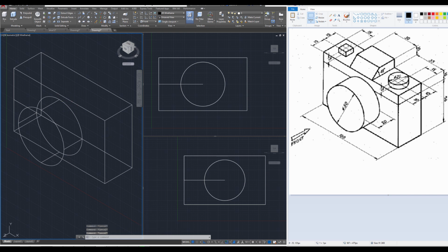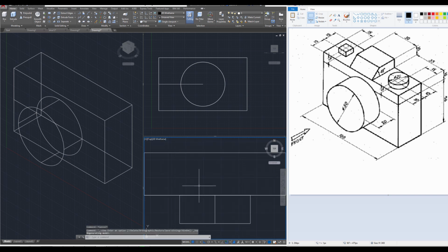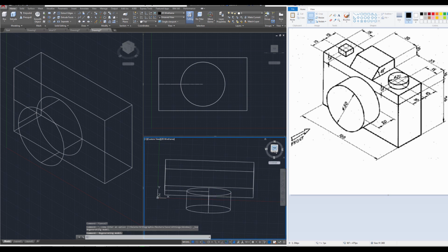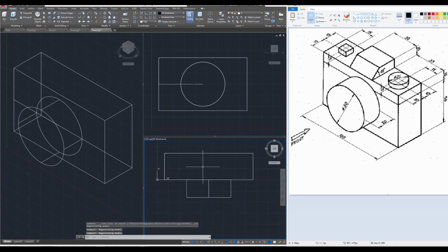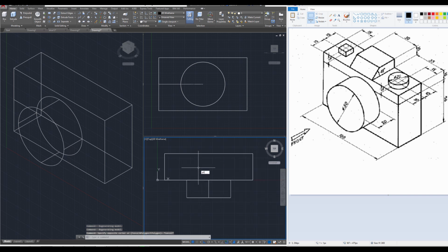Next, let's go ahead and add in our 2 buttons. That is on the top of the camera, so on this view, switch over to top. And if you're not sure if that's the top, I could rotate it to prove it. It's the top. Okay? And while this view is selected, let's go ahead and put in our markers to specify exactly where we should be drawing this. I'm going to use the polyline command again, P-line, enter.